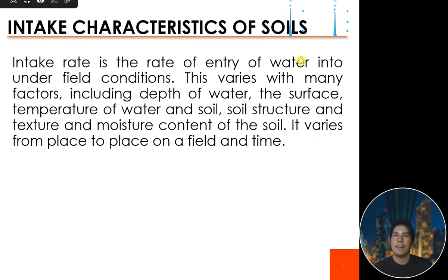So, we have also this intake characteristic of soil. So, intake rate is the rate of entry of water into the soil under field conditions. This varies with many factors, including the depth of water on the surface, the temperature of water and soil, the soil structure and texture, and moisture content of the soil.